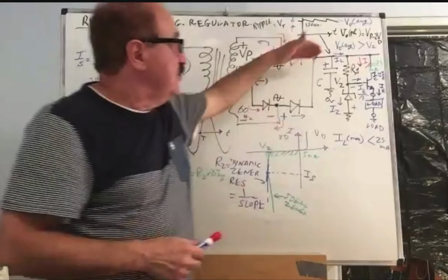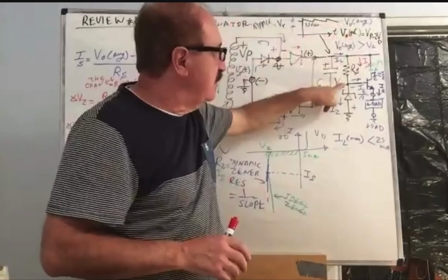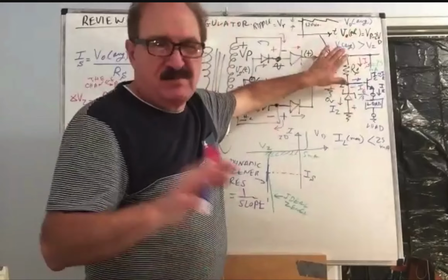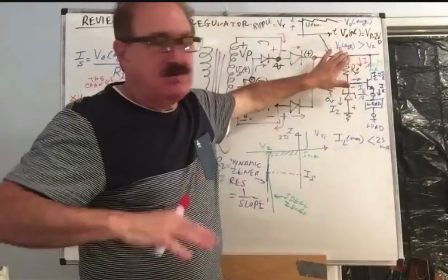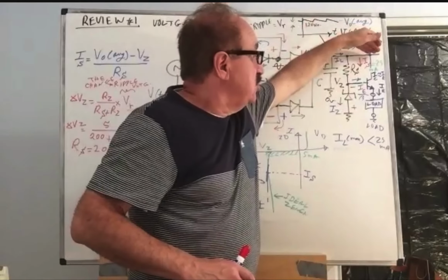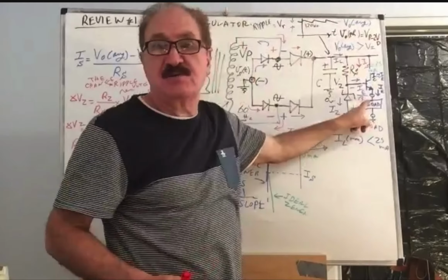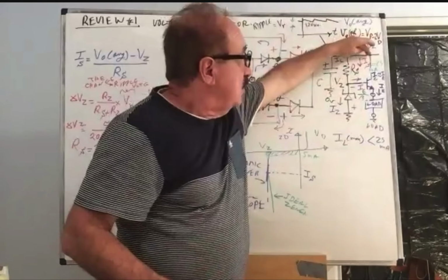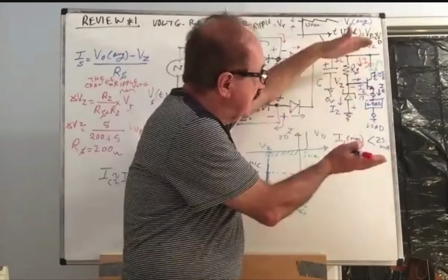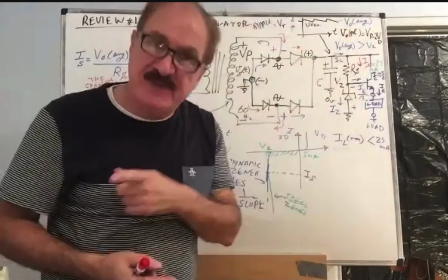So the ripple voltage, that fluctuation, which has a negative bearing on the stability of the zener, translates to the zener reduced by many factors. The change in the capacitor voltage, which is changing the collector voltage, will not influence the load voltage. Why? Because when the collector voltage fluctuates, VCE of the transistor will change. But we know that IC of a transistor is independent of VCE.